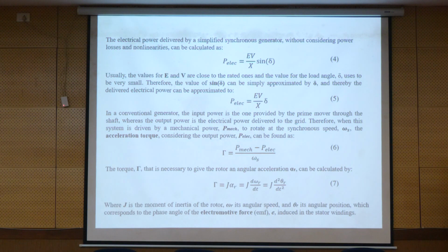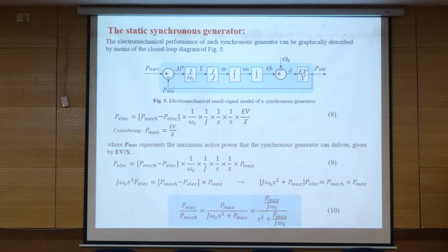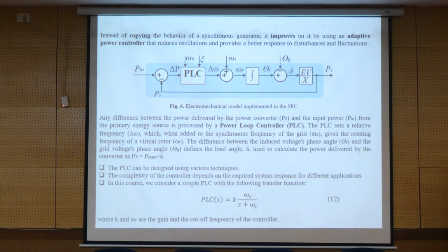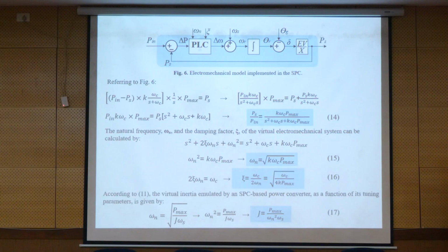So normally the omega n is not a constant value, because when you change the value of the load, then the voltage is impacted, and then delta is changing, and also P is changing. So you are not expecting something extraordinary exploding in the grid. Some changes provide this, which is why we sometimes call it small signal. Yeah. And this model will be able to provide or compensate inertia.